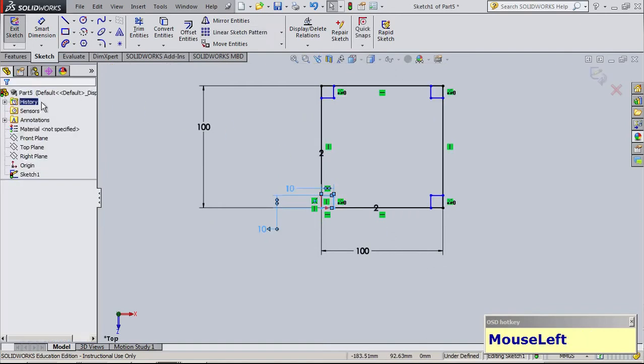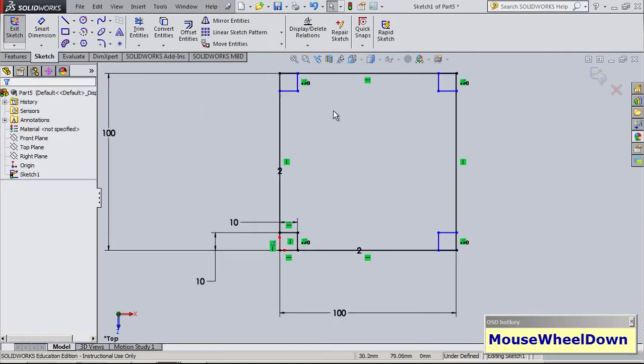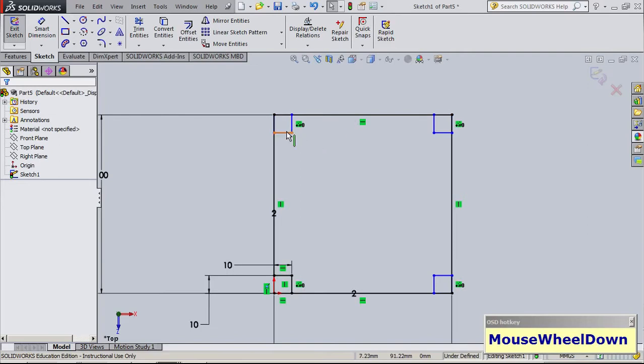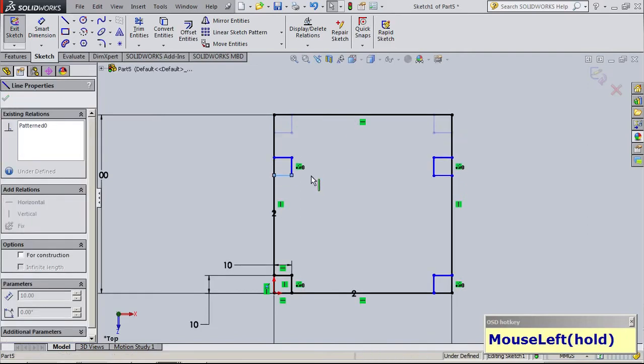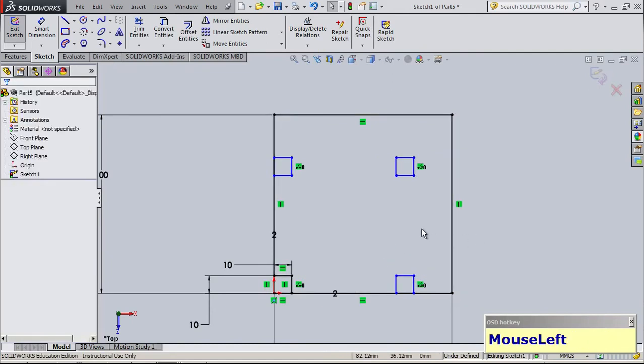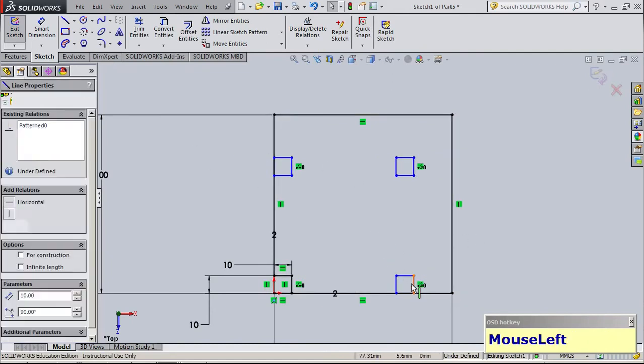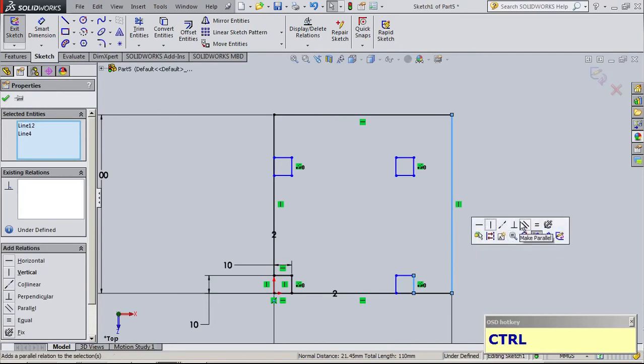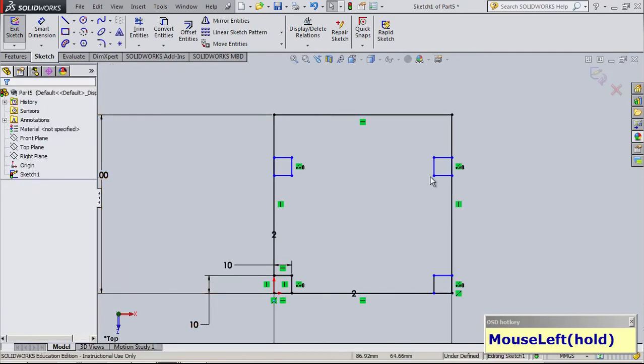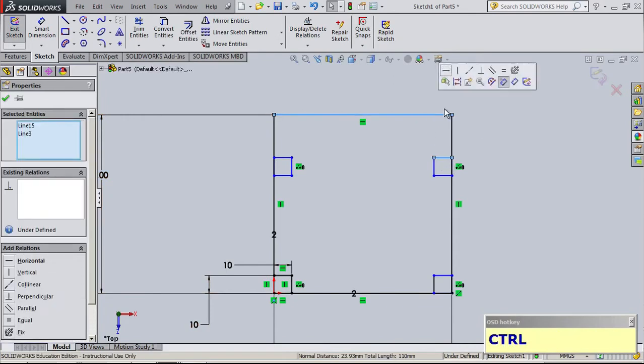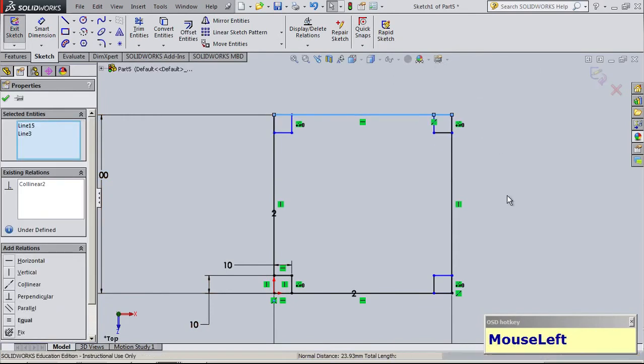And then say OK. Now this is automatically created. This one, the dimensions aren't really fixed, right? So what I can actually do is if I make this and this to be coincidental or collinear, and then I can make this and this line to be collinear as well.